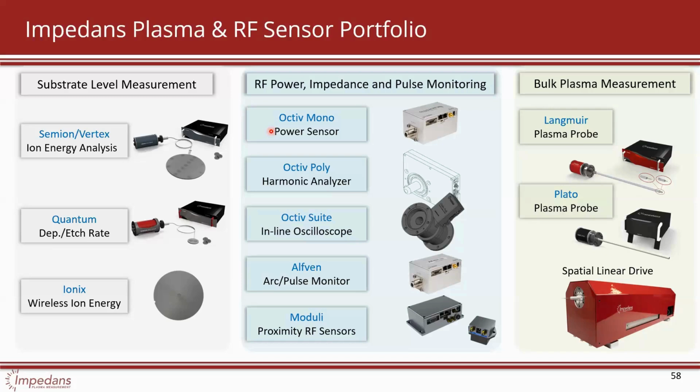Jose, thanks for the webinar. No problem. Vladimir, how do you trigger the measurement? The electronics box has a BNC labeled sync or TTL. You input a TTL and that does the synchronization, and you can set delays in the software. To start the measurement, you just press start scan.